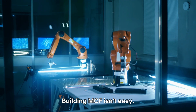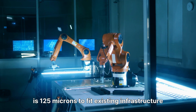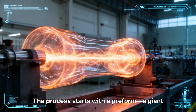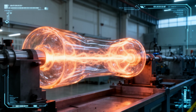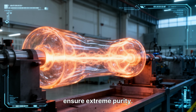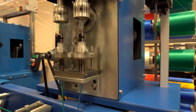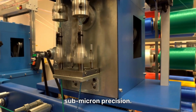Building MCF isn't easy. Designers must balance core count with diameter. Standard is 125 microns to fit existing infrastructure and avoid bending losses. The process starts with a preform, a giant glass log with the core pattern already inside. Techniques like vapor axial deposition, or VAD, ensure extreme purity. Then, it's drawn down a tower, melting at thousands of degrees to become the thin strand we use. Squeezing multiple cores into this process requires sub-micron precision.